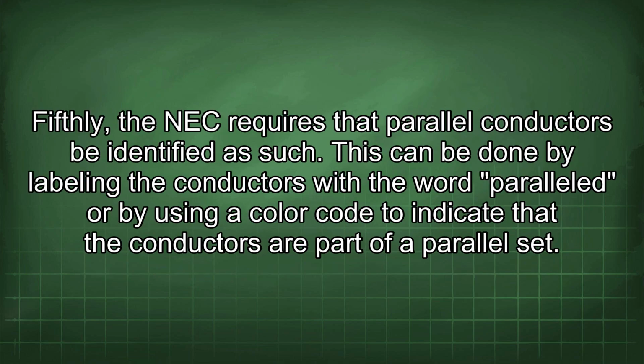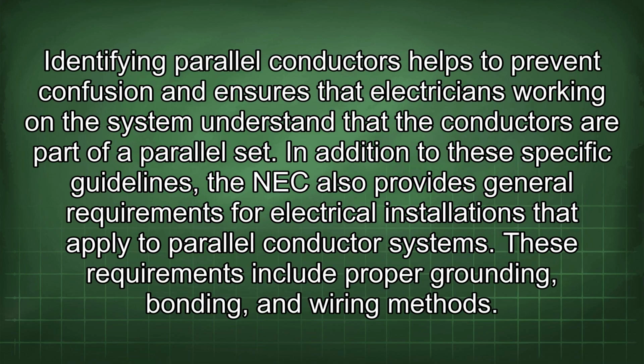Fifthly, the NEC requires that parallel conductors be identified as such. This can be done by labeling the conductors with the word "paralleled" or by using a color code to indicate that the conductors are part of a parallel set. Identifying parallel conductors helps to prevent confusion and ensures that electricians working on a system understand that the conductors are part of a parallel set.